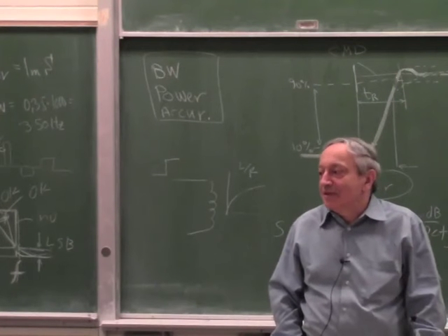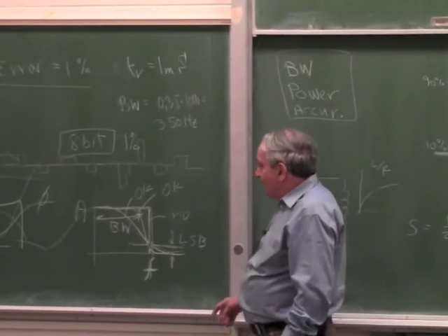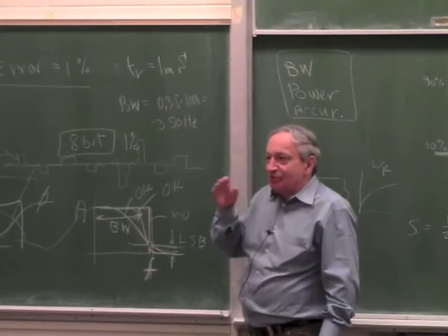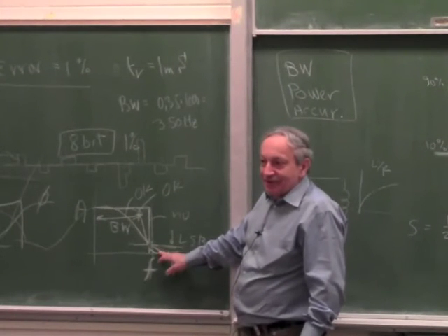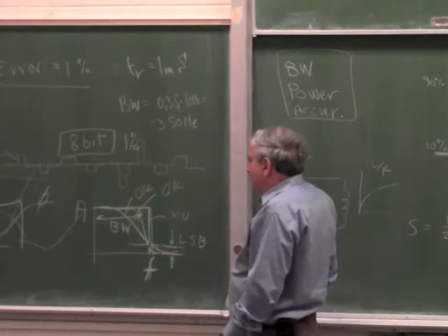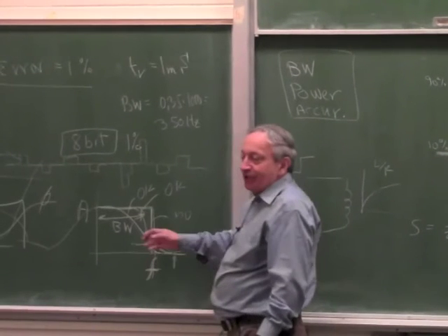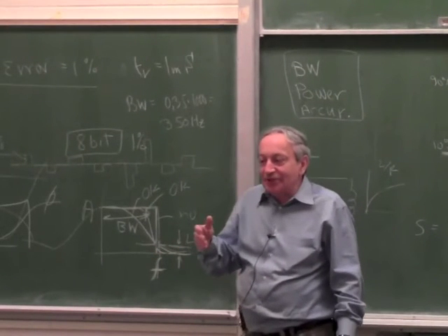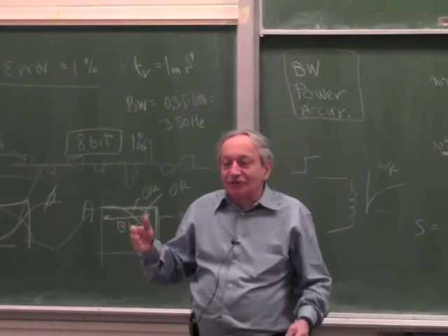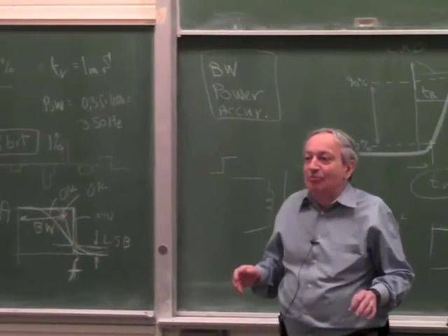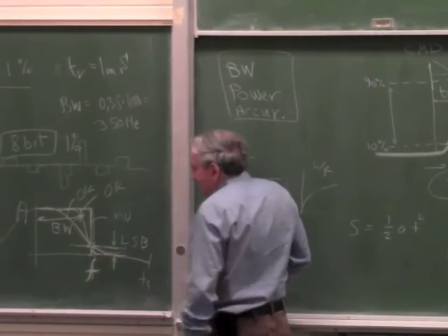Very good. So what you want to do is, at the sampling frequency, it has to be small enough that this will cause no aliasing, no error. Actually, it should be at half the sampling frequency, because from sampling theory, every signal should be sampled at twice the highest frequency. So if you don't want to introduce any aliasing more than 1 bit, it should be at half the sampling frequency.